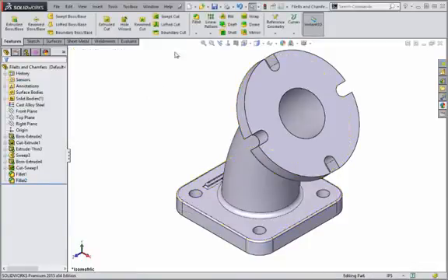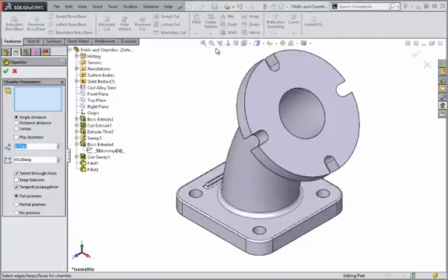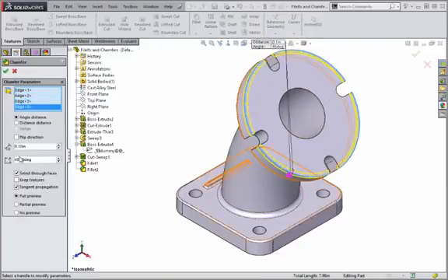Chamfers are applied nearly identically to the way fillets are. The only difference is how they're defined. Since adding a chamfer to an edge creates a flat face rather than a rounded face like fillets, you have to define an angle and setback distance for the feature. You can choose to use a combination of angle and distance, or use 2 setback distances.